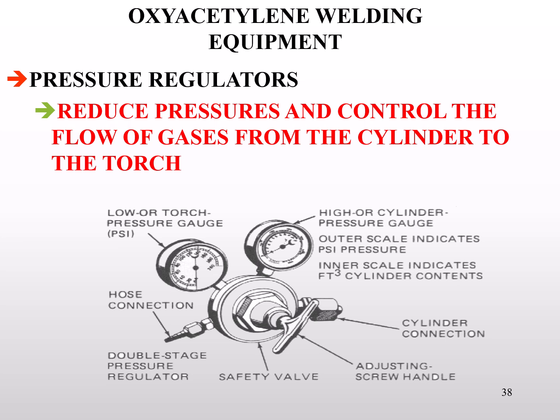With these types of regulators, we've got at-a-glance information. Our working pressure may vary based on the equipment that we attach to the hoses. So we'll have a work pressure gauge, then we'll have a bottle gauge. Once again, these regulators are made primarily of brass because brass doesn't spark. You turn the knob on the regulator in to increase pressure, out to decrease.